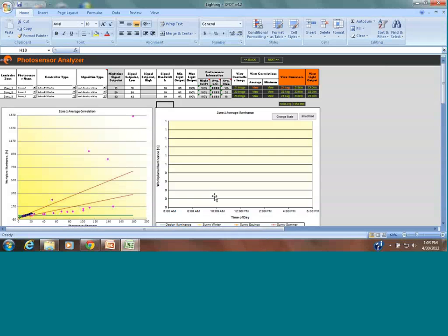Right. In that instance, what I would suggest is, at least from a daylighting standpoint, you could still use this and use generic light fixtures and see if it works with your design. Yeah, and even though it didn't work in that one space I tried it in, there's some other spaces in some of the projects where I could still use it and just do a basic analysis of some spaces that we're actually having some questions about putting some solar tubes in for extra daylight. Okay. You can simulate a solar tube as a light fixture. If you go to SolarTube's website, they will issue an IES file for the solar tube. So that'll be easy to simulate that as opposed to using it as a skylight. Okay. Yeah, we'll do.